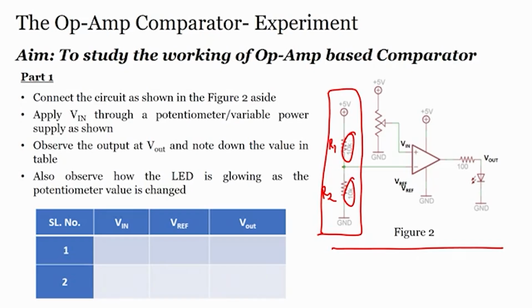and we are taking the voltage across resistor R2. So, what is this? The circuit we have seen yesterday, or in the last modules. What is this circuit? The circuit is nothing but your voltage divider, or potential divider, right. So, here your formula would be R2 divided by R1 plus R2 into V in. Here what is V in? V in is plus 5 volts.